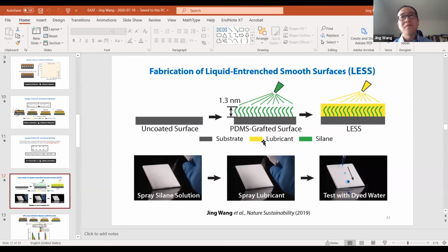So I think what you mentioned about crack propagation on the interface of the PDMS mainly applies to cross-linked PDMS, which is a bulk PDMS with much greater thickness. Here we used a grafted PDMS, where one end is covalently bonded to the substrate and the other end is free and mobile. So it's not like the cross-linked one.